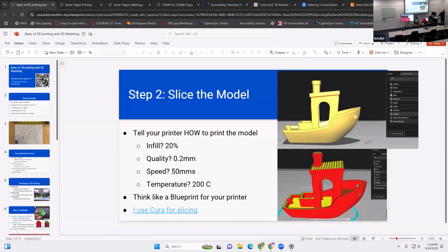But also that guy was filled with 0% infill, so it feels really, really light, right? So 0.16 layer height and then 0% infill. So it took a really short amount of time, but it's also really frail and kind of weak feeling. But also really, really detailed. And in fact, it's a perfect thing to put on your desk, as a desk decoration.